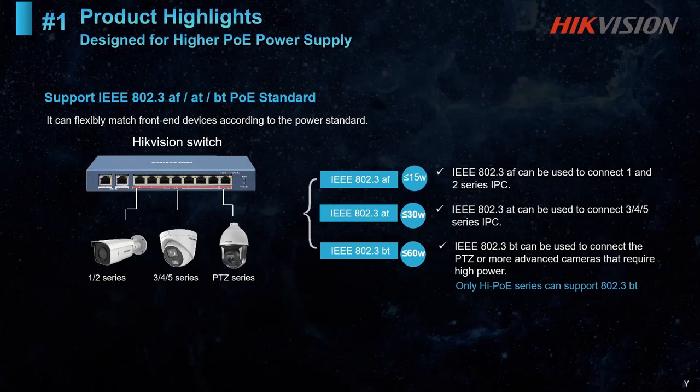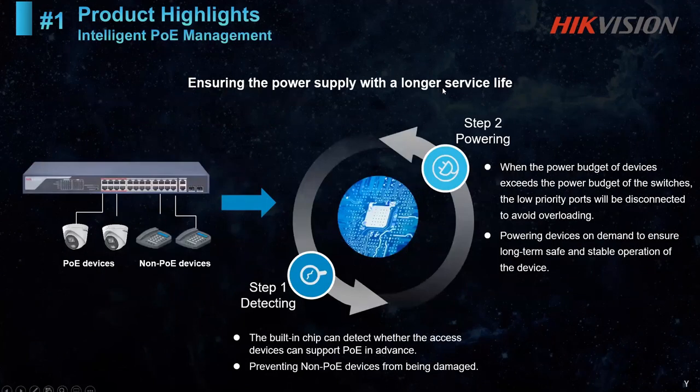So that is the initial advantage, otherwise we can say a highlight, of using a Hikvision PoE switch. Going forward, our switches are very well capable of handling the PoE power intelligently. There are many things that come to mind when we talk about PoE. Let's say we plug in a non-PoE device, whether it will burn the device, and how it handles it when the PoE power is not enough.